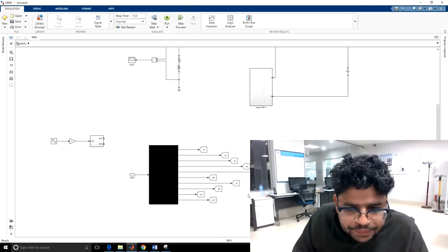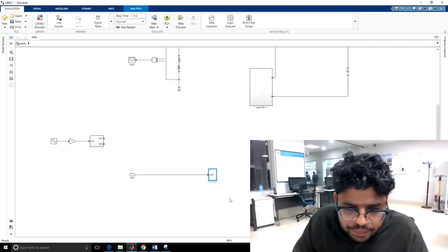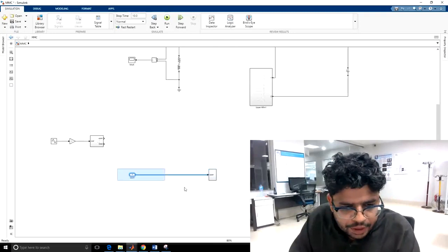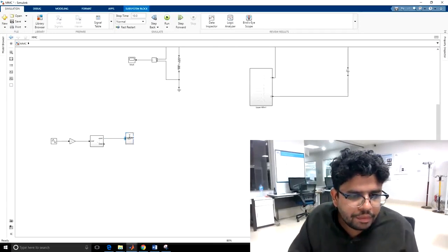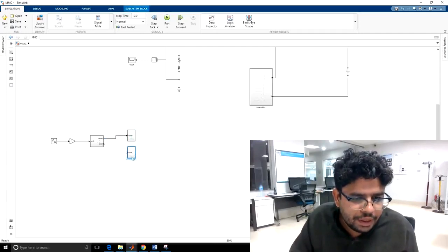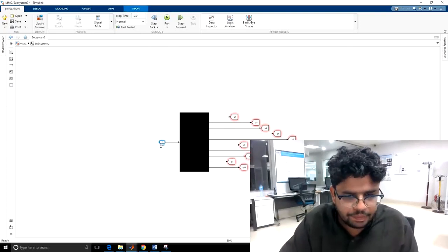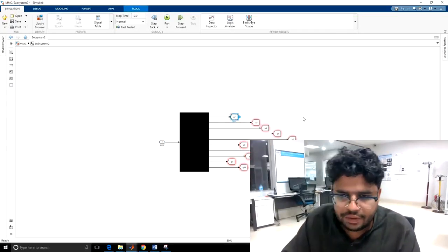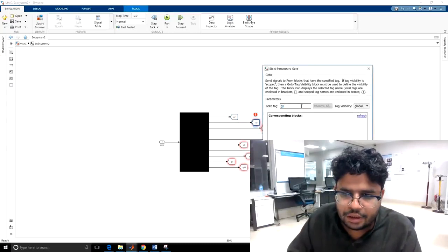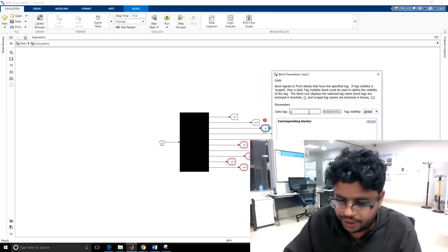All right. So let's make it a subsystem, and let's give these gate signals to the upper arm, and similarly we need it for the lower arm. Let's name it lower arm. And we need to change these gate signals to G11, G12, because for the lower arm the gate signals were from 11 to 20,